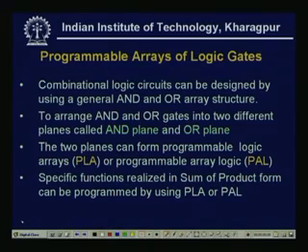So, we arrange AND and OR gates into two different planes called the AND plane and the OR plane, and the whole structure is called programmable, because we can program, we can change the product terms as well as the sum terms. Now, the two planes can form programmable logic arrays or programmable array logic.